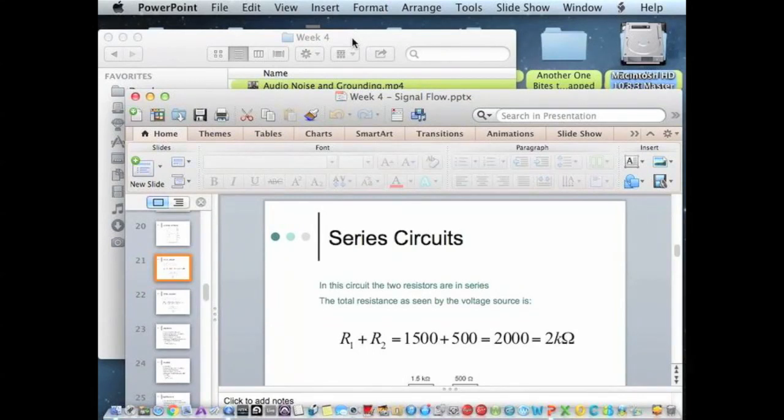The same thing applies for a wah pedal, like what Hendrix used to use, wah, wah, wah kind of sound. With his foot, he would move the resistance, and it would change the resistance of the signal going through, and it creates that sound. But those are two really simple ways that just a resistor and a capacitor change what you end up hearing. But it gets more complicated than that because a lot of the electronic devices get power, and so they have active filters.